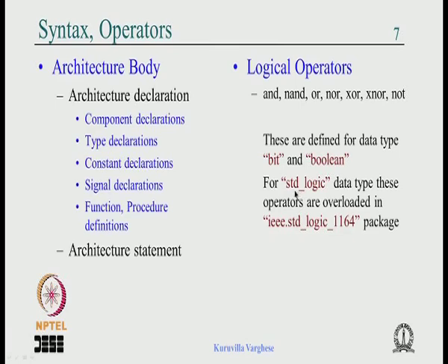We are going to use the data type called std_logic, standard logic. But you do not have to worry about the logical operators for this data type, because in the IEEE std_logic_1164 package, which we used in our first example code, these logical operators are overloaded.